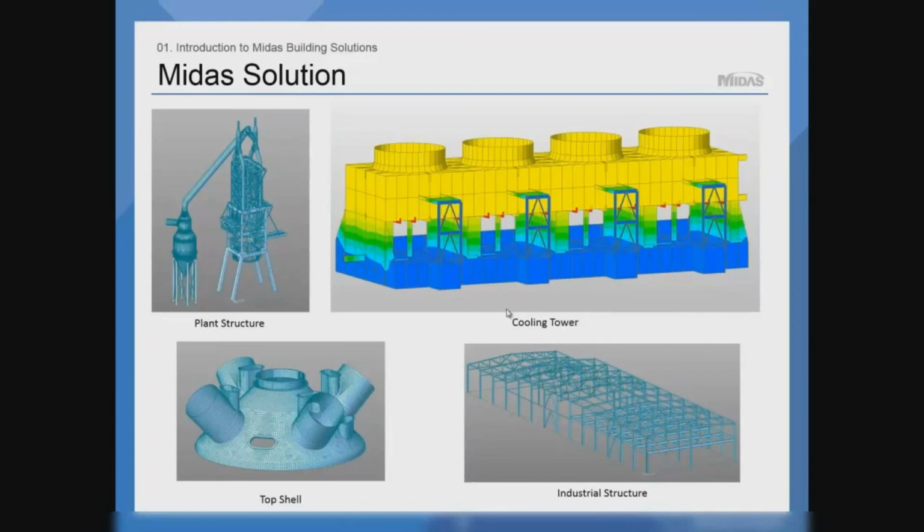Even for the trusses, we only have to click on the optimization. The program will automatically give the optimized section, as well as if you want you can choose it from the data table, and it will give you which is the suitable section for that particular forces. And one more thing is, whenever you see the result for the steel structure, it will give the clause number also, means for which clause it will take the values. So the entire thing you can get into the table in the WordPad document format. So these are the things available in the Midas.